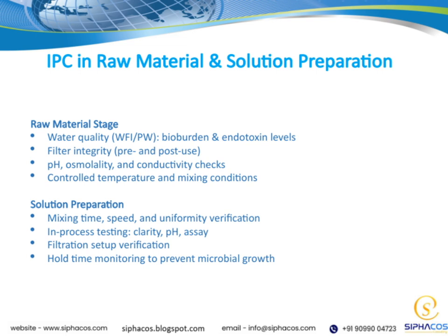Moving on to solution preparation, it's important to verify mixing time, speed, and uniformity. Proper mixing ensures that all components are evenly distributed, which is vital for product quality. We also conduct in-process testing, such as checking clarity, pH, and performing assays to confirm the solution's correctness at each step. Setting up filtration properly is another key point. Any errors here can compromise the entire process. Lastly, we monitor hold times carefully to prevent microbial growth, making sure that the solutions stay within safe limits until further processing. Throughout both stages, in-process controls, or IPC, play a vital role.